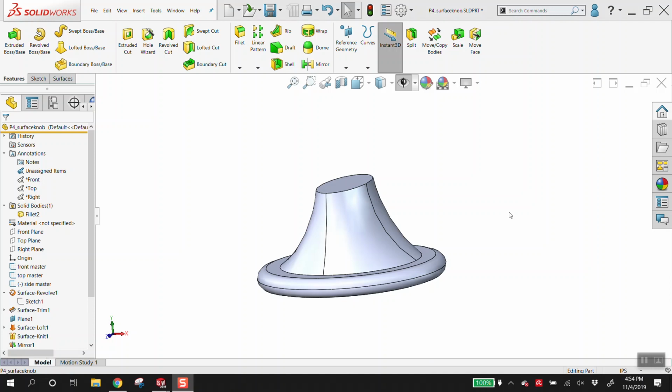The only time surfacing is okay is if it's something loose and you're doing it for yourself. But solid bodies are expected. So don't turn in a project with just the surface. In my class, I won't like that. If I left in a surface by accident, it would be deducted. Let's say for project 4. I know that there are some surfaces in project 3. That's okay. Again, it's just for render, but for the most part, best practice is to make it a solid body.